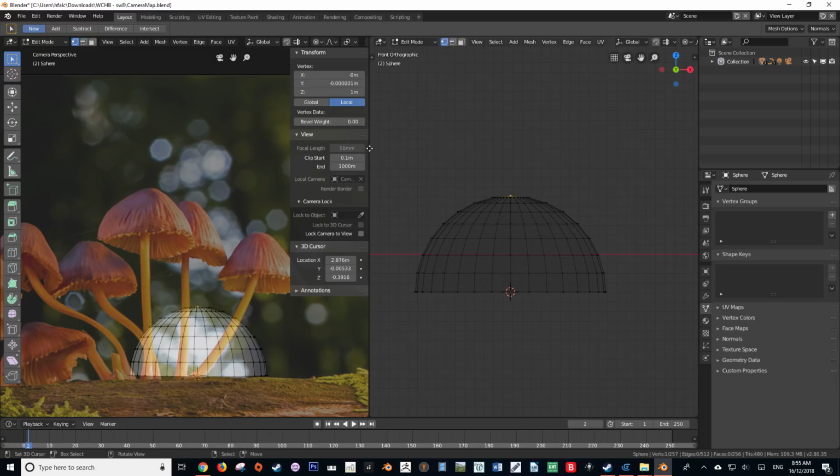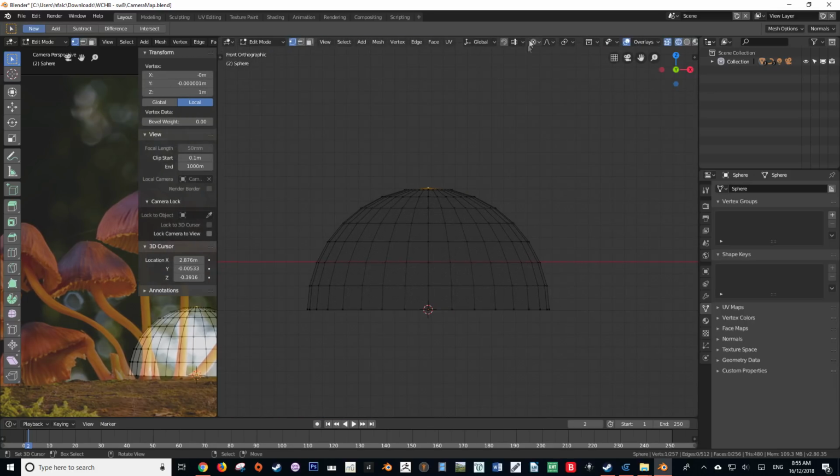And you'll know that proportional editing is on because if I just scroll up my screen here, you'll see that little flashing icon up there. That's our proportional editing icon. And if we click that icon, we actually are given more options. So there is an enabled and a connected option. Connected will only apply the proportional editing to geometry that is connected to the selected piece. So very useful if you have multiple pieces of geometry in the same object.